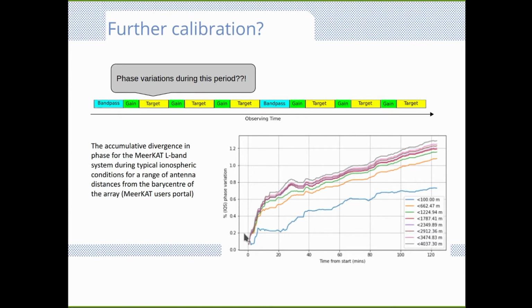We have noticed that there are residual cable delays that change on the order of tens to hundreds of picoseconds. So that is still substantial. If you're trying to do really high dynamic range imaging on a field that has bright AGNs in it, and you want to go down to see your star formation population, for instance, it is still a big problem, just because those bright AGNs are going to highlight any residual errors that you have in your data.